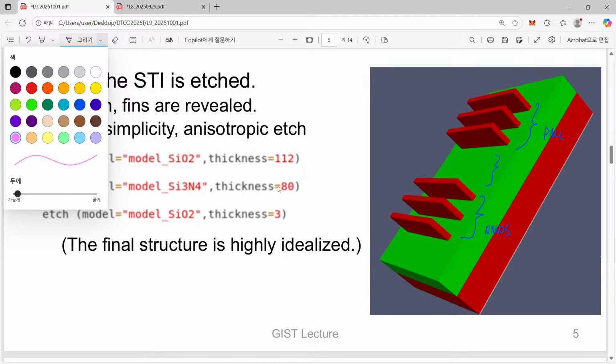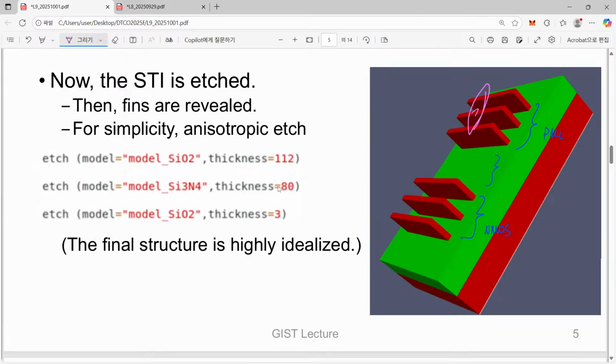It means that here we have a PMOSFET and here we have an NMOSFET. Both of them should be driven by the same gate signal. You know, in order to make an inverter, we have to provide the same gate voltage to both NMOSFET gates and PMOSFET gates. So they are connected by a single metal gate connecting these two parts. So this part is used for that purpose.